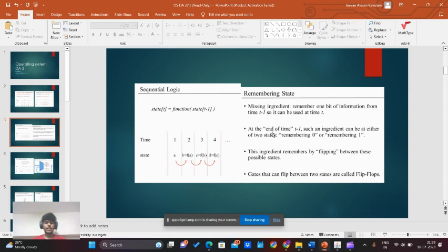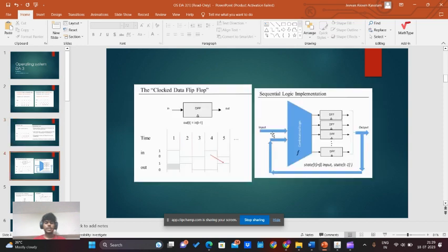Physical signals and electrical implementations of circuits do not change instantaneously between time units. There are delays involved in transitioning between different logical states. However, by choosing an appropriate clock cycle that allows enough time for stabilization, these delays can be disregarded and the system can be treated as if it operates instantaneously within each time unit.